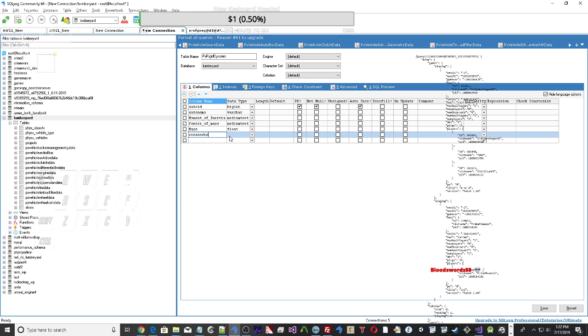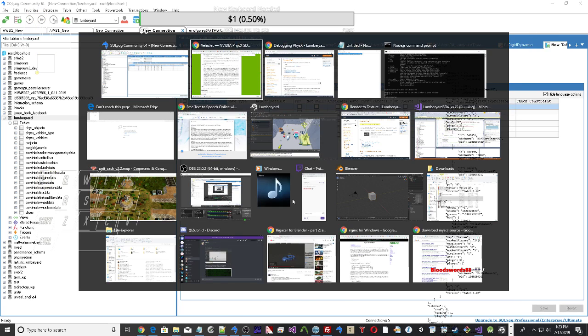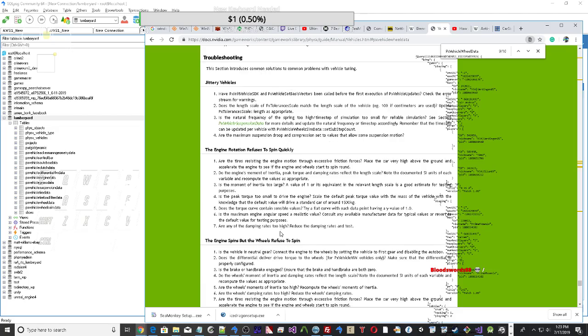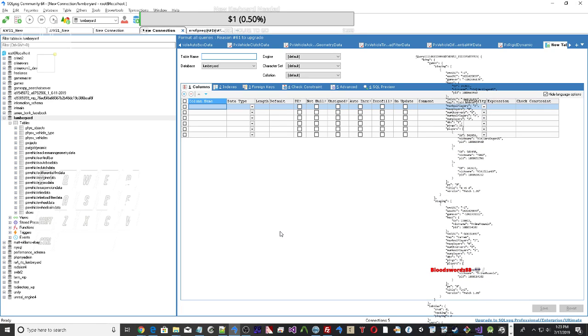Following this, a PxRigidDynamic actor is instantiated and configured with geometry for the wheels and chassis as well as dynamic properties such as mass, moment of inertia, and center of mass. The final step is to instantiate a PxVehicleDrive4W instance and associate it with the actor and the vehicle configuration data. The functions setupWheelsSimulationData, setupDriveSimData and setupVehicleActor are actually quite involved and shall be discussed in future sections.